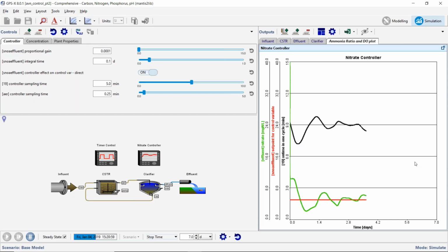I've seen systems that do this in a more sophisticated way in order to take advantage of partial nitrification, doing nitritation, so you can get that first step of the nitrification process and land on nitrite and keep it there if you want. The AVN process is an example of that, where you might want to use this intermittent aeration to get a nice balance between ammonia and nitrite, and then feed that into an anammox reactor, and keep that in the right ratio so that the anammox system can be optimized for the best performance.